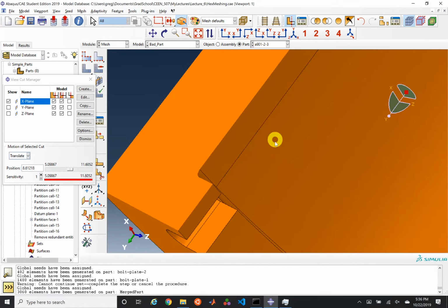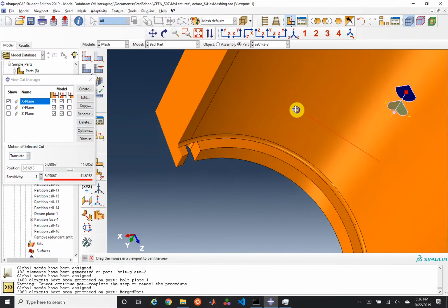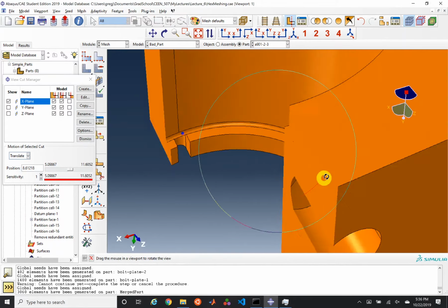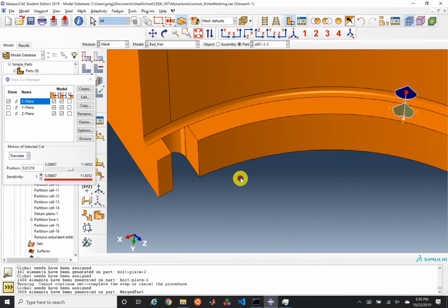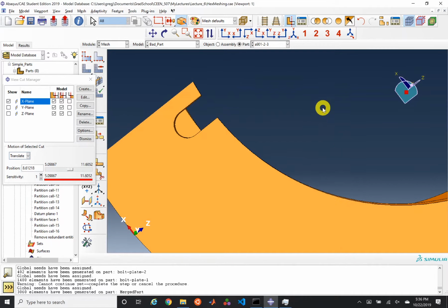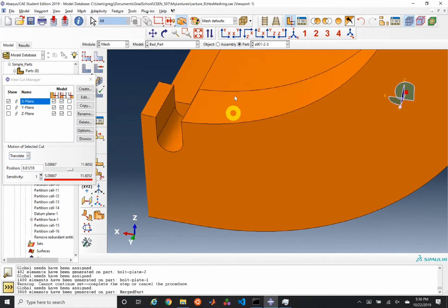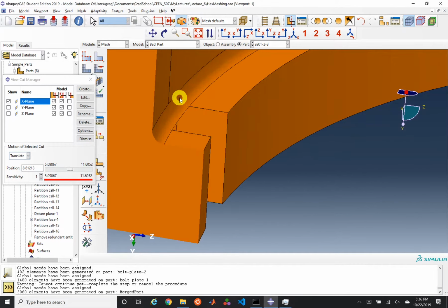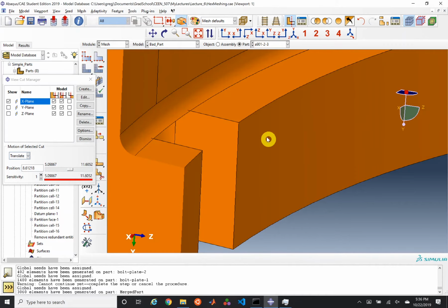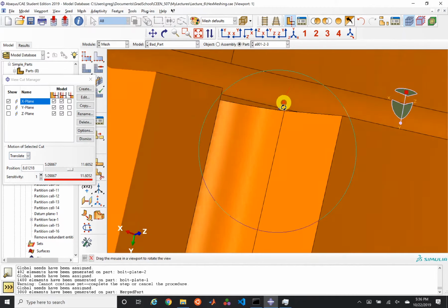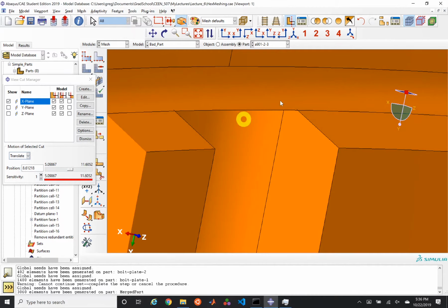So here's a case where on this surface I have a fillet defined between this surface and this surface. And so my fillet goes all the way around. But the designers also defined these inset holes that are going to be machined either through drilling and then pushing out or boring in. But just think about it, how in the world are you going to manufacture this part? How do we propose that we're going to be able to machine something down to effectively, if it's a fillet, to 0 thickness here?